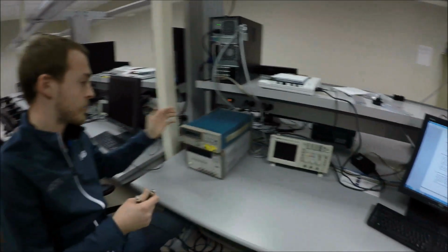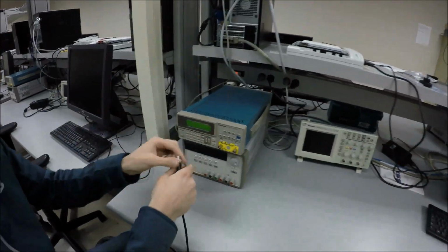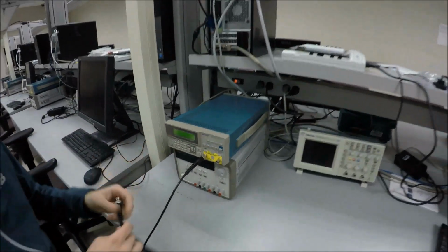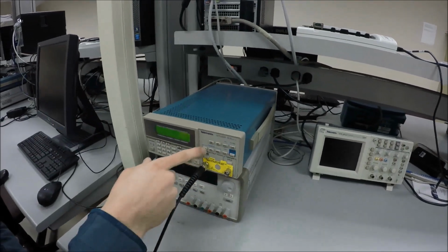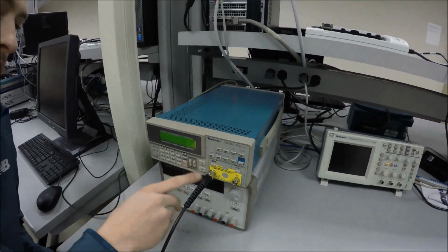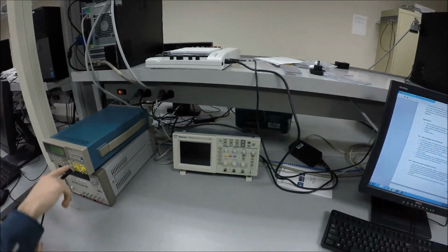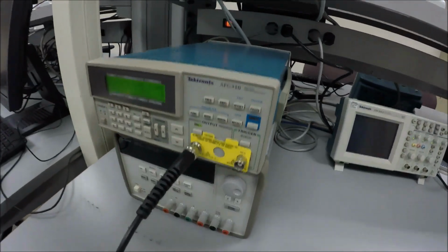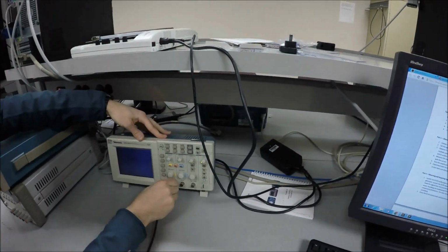To start with the arbitrary function generator, which we'll use first, you simply press the power on button and connect the BNC cable to the channel 1 output. Once you have this connected, you can press these buttons up here to change the frequency, amplitude, and the offset. You can change the type of function, whether it's a sine wave, a square wave, or a triangle wave, using these cursors down here. It's pretty straightforward. Once you have your function set up, you turn on the channel 1 output over here. So you press this channel 1, the light will turn green, and that will show you that the output is on. Once the oscilloscope is up and running, plug it into channel 1.